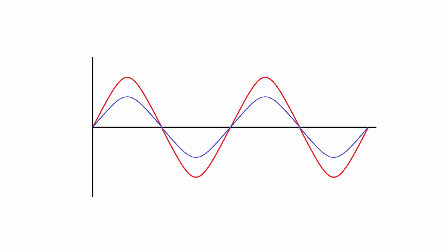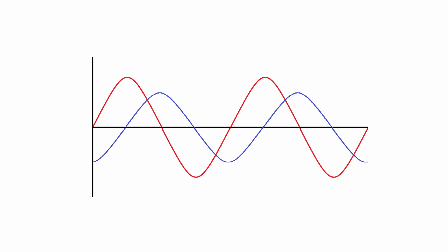Let's take a look at our light bulb again. What's the phase difference here? The phase difference is 0 because they're in phase, they have the same timing. Meaning we take the cosine of 0. What's the cosine of 0? Well, that's 1, of course. So the power factor is 1, or cosine 0. In our second example, the phase shift was 90 degrees. I made it 90 degrees. Cosine of 90 degrees is 0. So here, our power factor is 0.